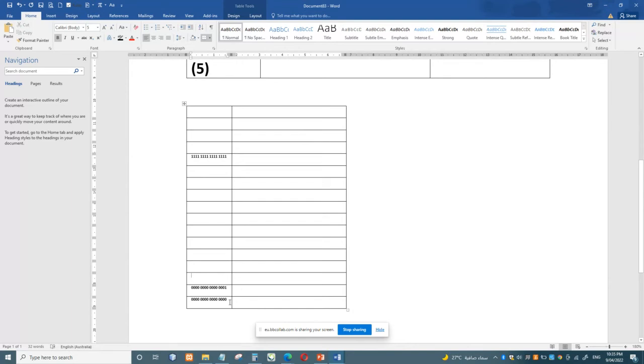That is exactly what we are doing in indirect addressing. We spend only 8 to 10 bits for referring to the lower part of the memory, which can be referred with 8 bits or 10 bits, and they will basically contain the actual address that you want to access. For example, the actual address that you want to access, which is 32 bits maybe.